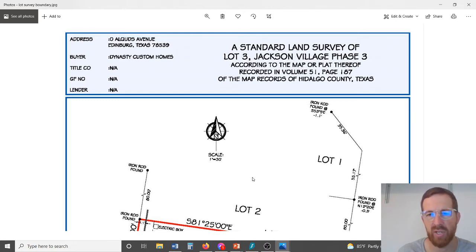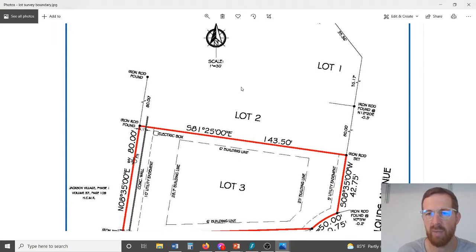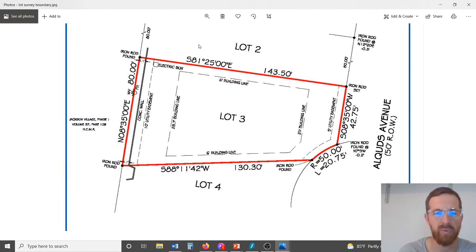So as I said, usually they need a survey in order to get a building permit. And the surveyor has marked those property lines so they can put a fence in and different things in and figure out their building offsets. So you can see 6-foot building line. This is actually the offset. So they've marked that here, and they've probably marked it somewhere, not usually with a stake, but maybe they marked it with some spray paint on the grass or something for the builder. So he knows that he can't build beyond that. There's a 6-foot offset probably in this county.